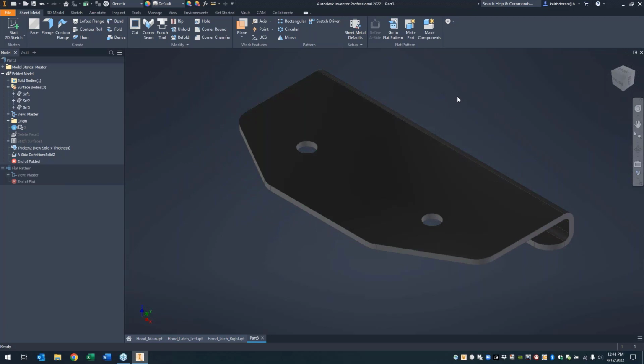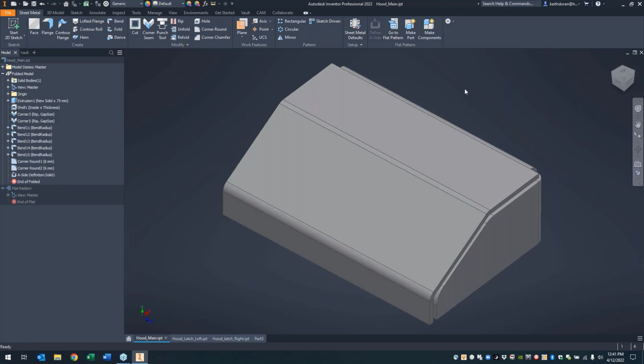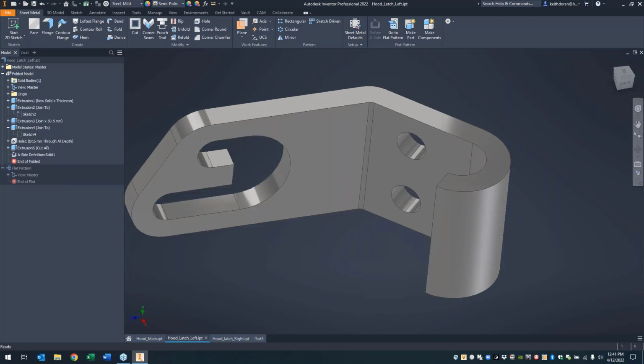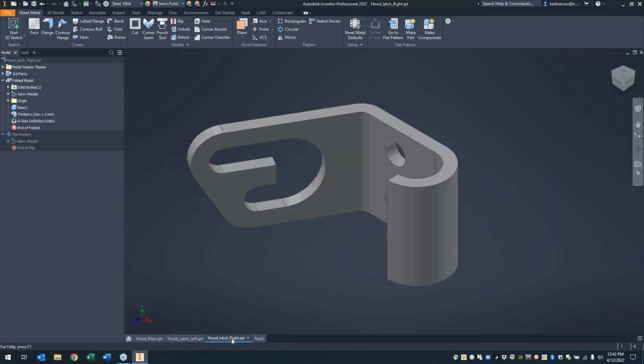So in this case, we went through a number of different instances. We started out using an existing 3D solid that was not sheet metal fabrication at all, and we used the corner and bend tools in order to clean up that object. We then looked at a neutral file or a badly modeled component that was supposed to be sheet metal. We went through and diagnosed some potential problems with it. In our case, we found that these edges were not uniform thickness through the bends. So we adjusted and fixed that and created a component that was then flattenable.